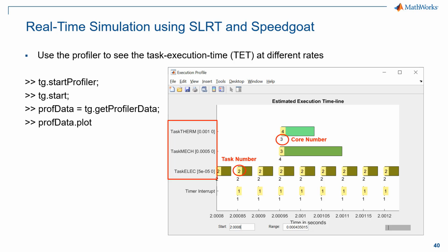So to re-emphasize with those sample times that we're seeing here, task execution times tell us that we would be unable to simulate the full system in real time if we did not split sample times across the different model sections, and if we were unable to use slower sample rates for the thermal systems and Brayton cycle gas turbines. With explicit partitioning, we have further control of using the computational resources on the real-time system. And as model complexity develops, we may consider partitioning the model at different locations and including more than one sample time per core. These choices would, of course, be system-specific.